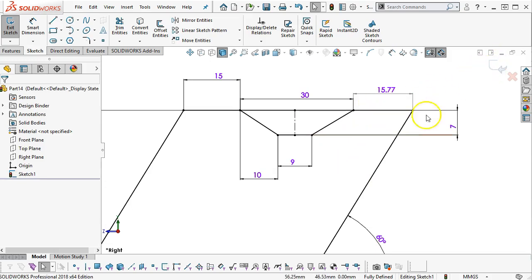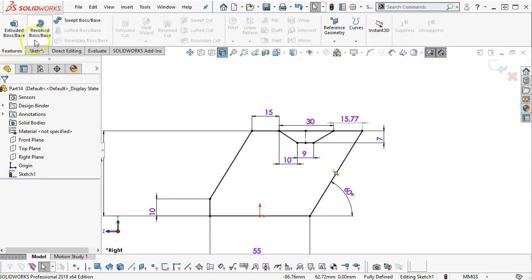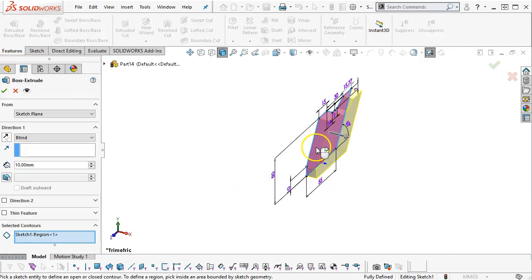1577. All right, we go into the extrude, we pick our region. As soon as it sees that overlapping, that intersecting geometry, it's going to automatically put us into contouring region. All right, so depth is 60 millimeters.